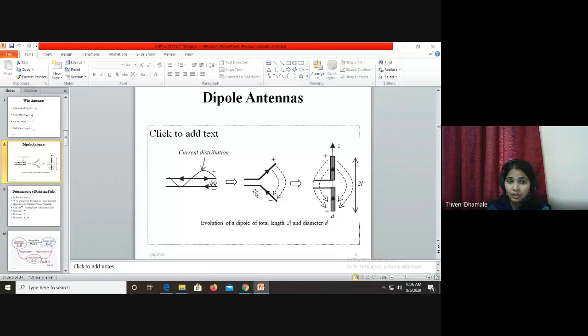So when we give the tapered structure, this arrow means the fields are like this. Again, we have given the shape of these simple two poles, that is the dipole, positive and negative. Whatever this dotted arrow shows is the electric field, right? How that field is detaching from this antenna in the far field. So the length from this plus to this minus is the length of the antenna.